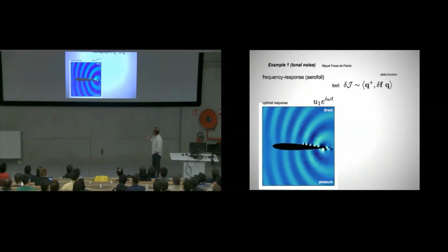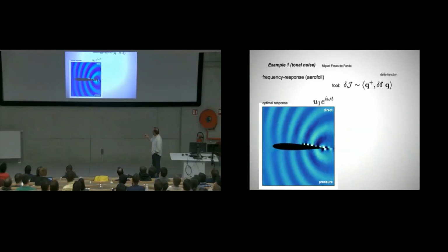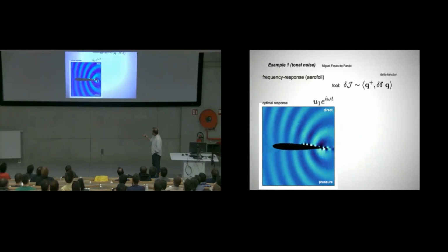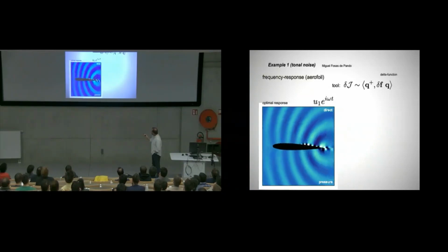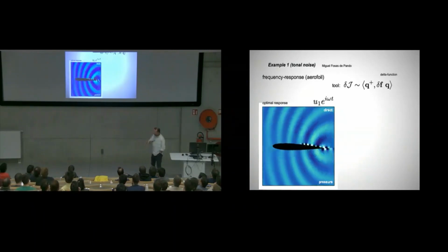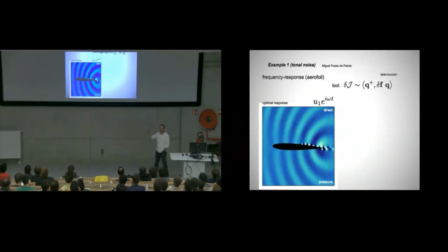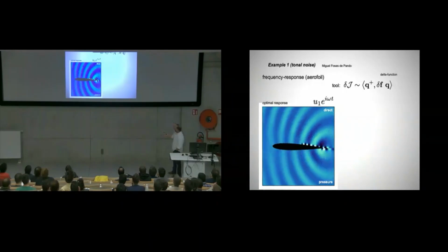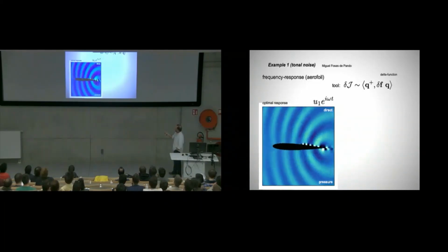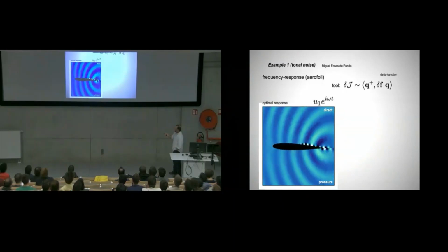So it has the boundary layer instability on top. Here it's rolling down. There's also a boundary layer instability here, but it's so small it only amplifies almost on the last little piece here. You see it here. Okay, so it doesn't do anything, and suddenly, whoop! In the last one, it really goes up. Then you have the acoustic wave radiating, nice dipole here, radiating forward and triggering it again.